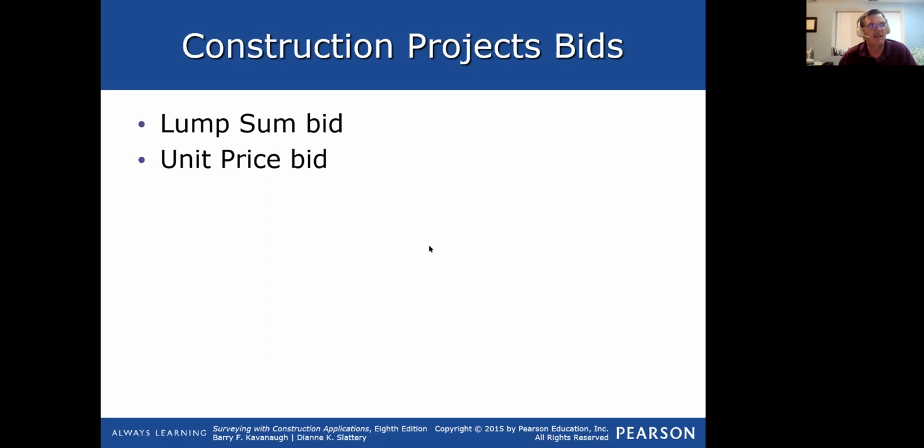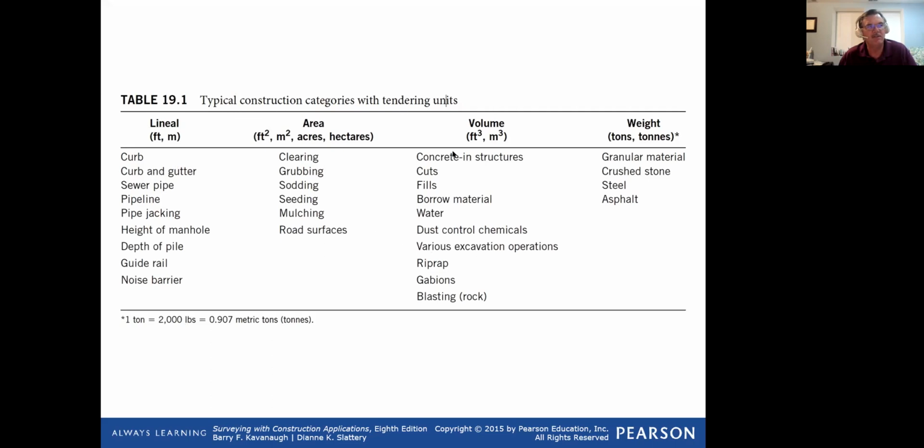So, the types of units we're dealing with: feet, or linear feet. You would never use meters too often unless you're working with the government or the military maybe. So dealing with feet, all of these things here, curb and gutter, your sewer pipes, are done by linear feet, and that's how they're sold, and that's how they're built.